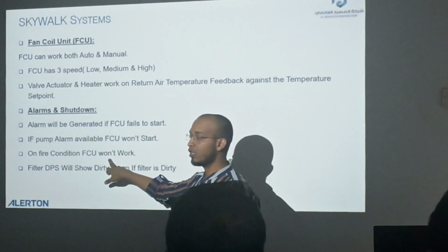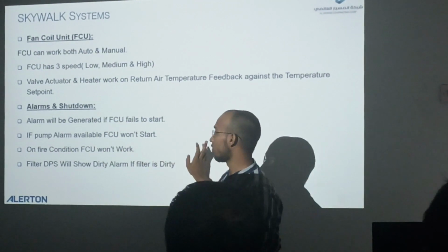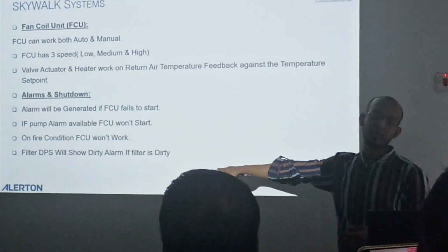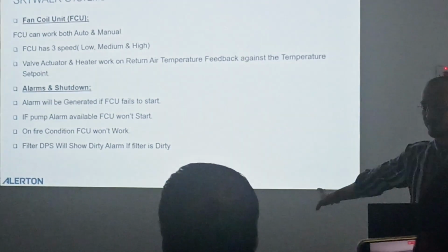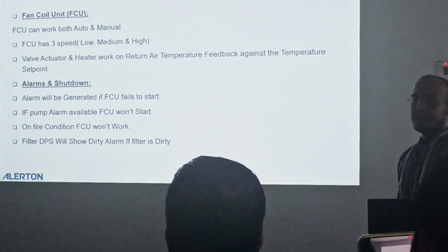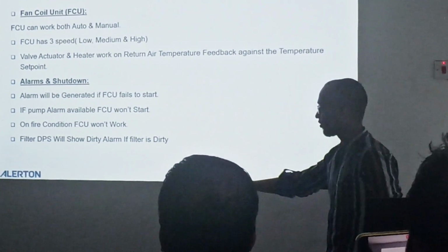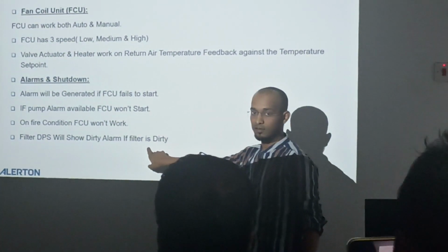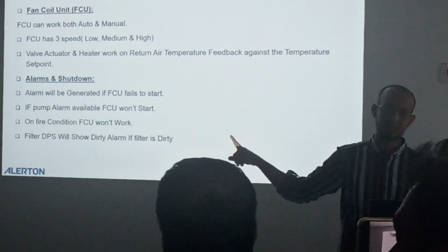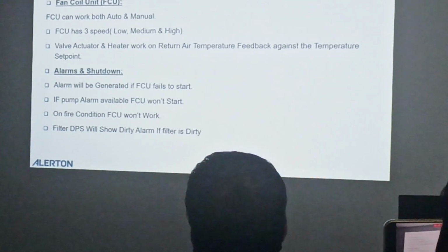Then on fire condition also your FCU goes off. Then you will get the alarm for the dirty filter as well. If the filter is dirty, it will be only an alarm. This is the alarm generator. The dirty alarm will be activated, that's it. It will not cause your FCU to turn off.